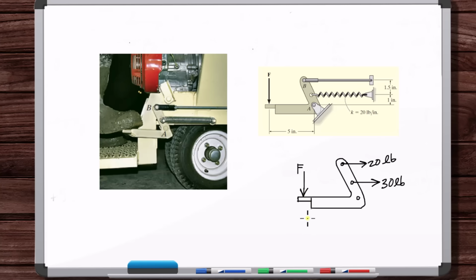So for unknown forces, you don't have to worry about the sense. Just put whatever sense you want. But again, you could still put this at an angle if you wanted to, but that adds another unknown. So if this angle was 0 degrees, and if you had sufficient knowns, you'd solve for this, and it would tell you that it is 0 degrees. But this is different than the sense. This is like an extra unknown. The sense of an unknown force is not an extra unknown. The final answer will just tell you. It'll say positive or negative.